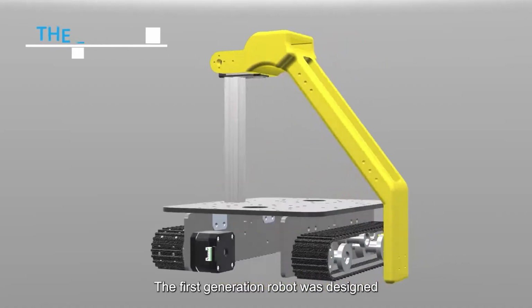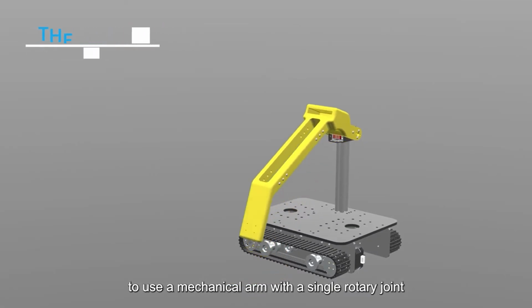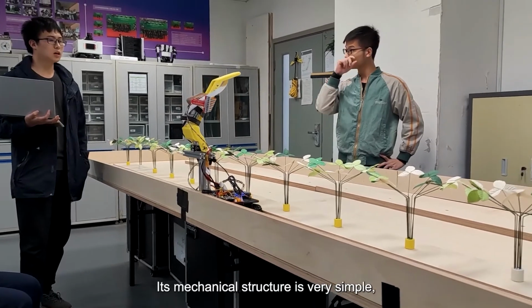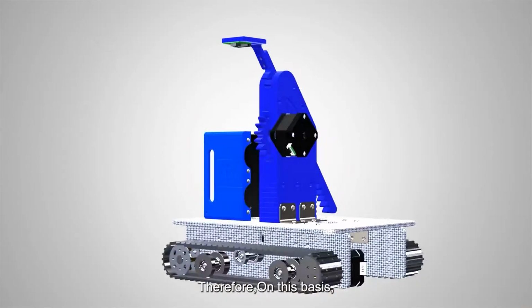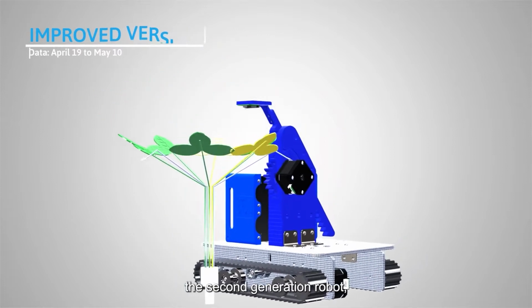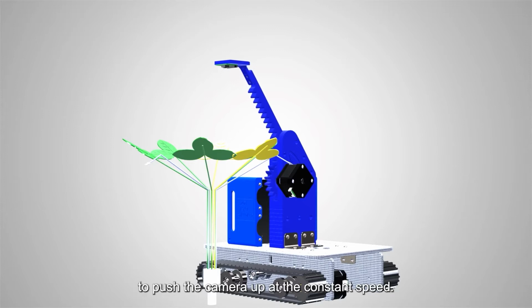The first generation robot was designed to use a mechanical arm with a single rotary joint to control the ascent of the camera. Its mechanical structure is very simple, but it has high requirements on the accuracy and quality of the steering gear. Therefore, on this basis, we have updated and integrated a second generation robot which uses a rack and pinion to push the camera up at a constant speed.